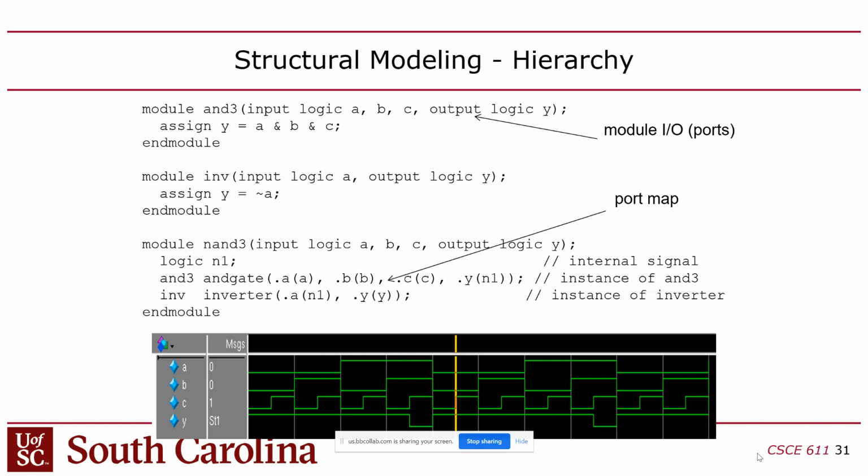Maybe it's when you have pulling up and having direct output. For example, if the wire is a strong 0, it's connected to the ground, but if you pull it up, it becomes a strong 1. Yeah, it's possible. The distinction is that these were generated through Tcl commands in the simulator, whereas this was generated through the module. So that's the difference.